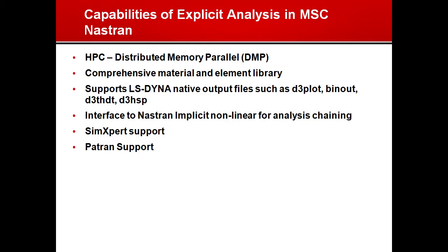Comprehensive material and element library, we'll show you a little bit more about that in just a minute. We do support the LS-DYNA native output formats, such as D3PLOT, BINOUT, D3THDT, standard outputs of LS-DYNA, and you'll see that's essentially what comes out of a Nastran explicit run. We do have this chaining. I'll show you an example of that, where we can take Nastran implicit, tie it to an explicit, and then go back to an implicit, so a chain of simulation. And we do have full support by our pre- and post-processors, SimX and Patran.